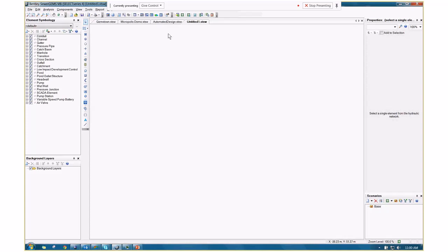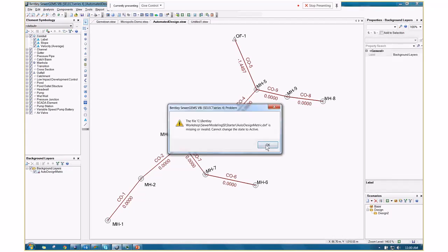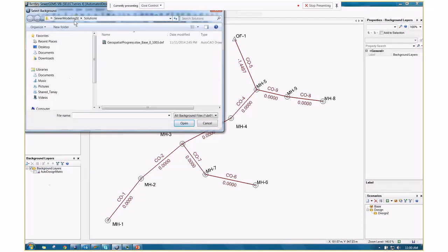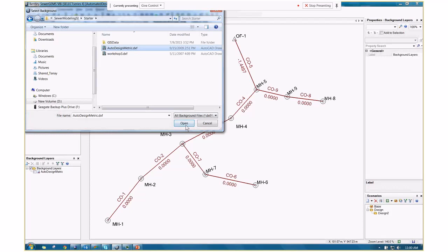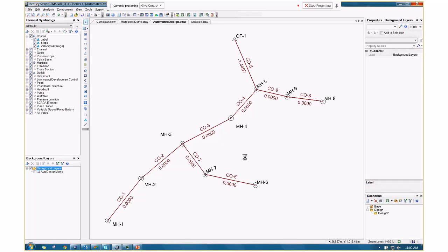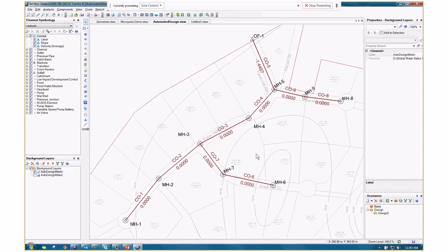Now I'll just navigate to a typical network like this. Can you see the network? Yes, I can. Now I have created this network by using an AutoCAD file as a background reference. Whenever we take some background file as our reference file, our network can be considered as a scale network, and you won't have to insert and allot all the lengths of the pipes individually, right? It will be automated.